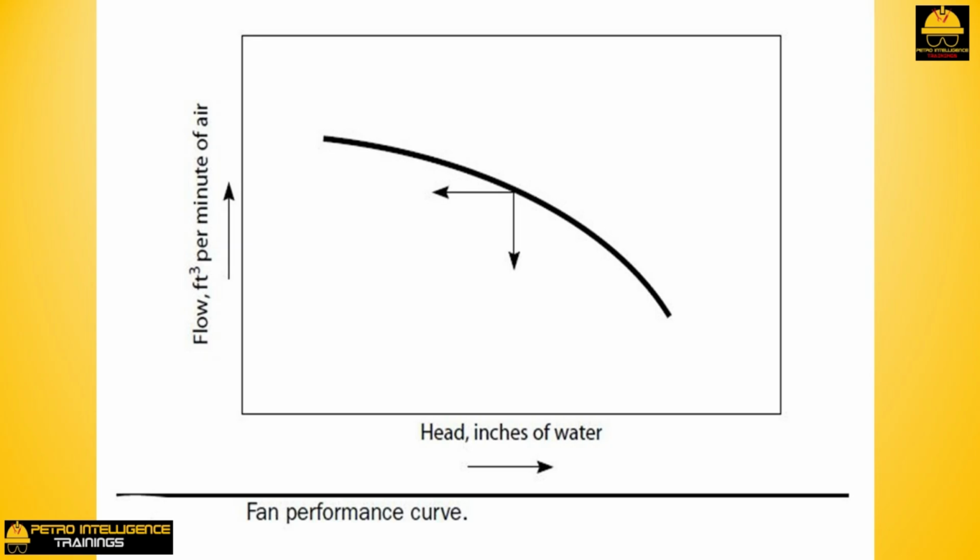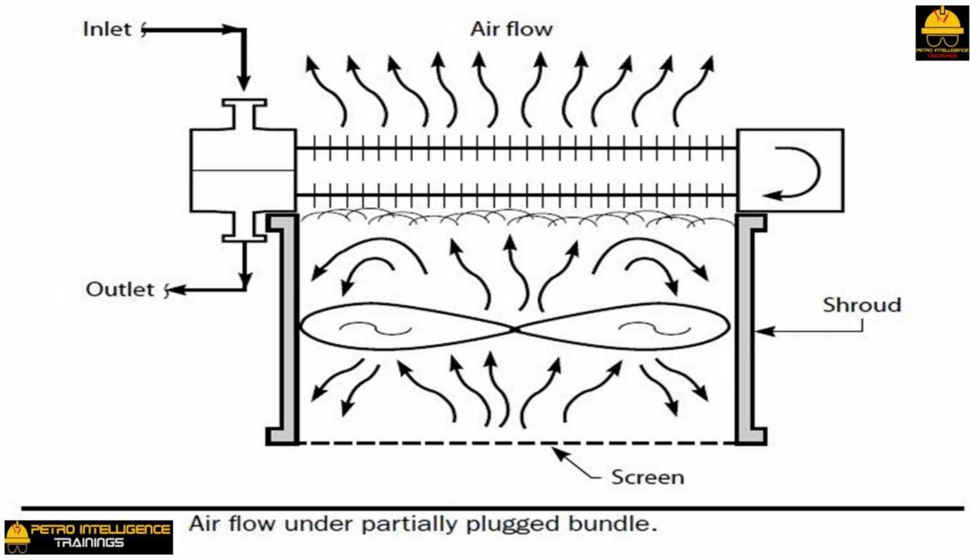Naturally, there is no reverse airflow on an induced draft fan. That can occur only in a forced draft fan. Reverse airflow can be observed with a forced draft fan by seeing which portions of the screen, shown in picture, will not allow a dollar bill to stick to the underside of the screen.